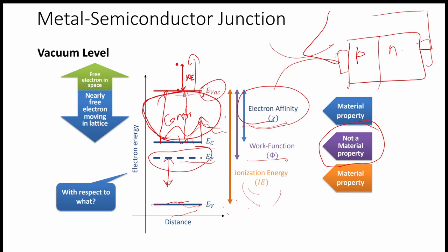We put in the metal to make it equipotential, because if we put the contact here, there will be a kind of current grounding kind of thing. There will be more resistance, sometimes less resistance, or there are so many things. So we put contacts, and it is very necessary to see what type of contact it is making. Is it blocking the current, or is the current flowing very smoothly between the metal and the semiconductor? It is very important for device purposes to understand the basics of the metal semiconductor junction.